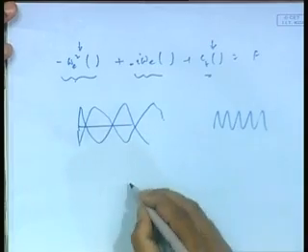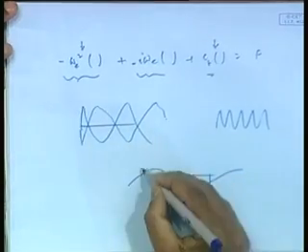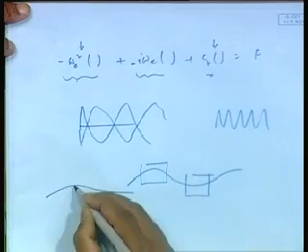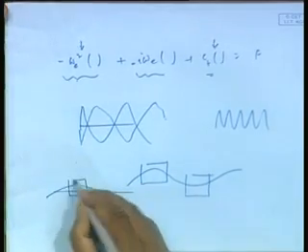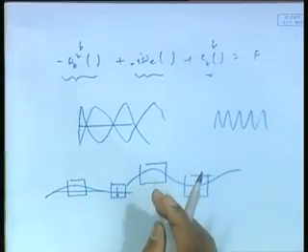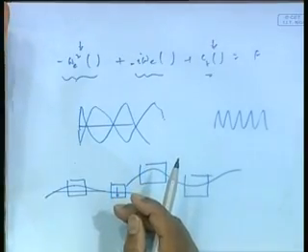This is very important. In the first case my boat was riding the wave, but now at the higher end my boat is out of phase with it. That means, when the wave is rising, the boat is sinking, which is more dangerous. You see, that is what I wanted to tell you from the physical point of view. That means, if I were to draw this here, in this case when the water is rising, my boat is sinking. Here when the water is going down, my boat is rising. So, I end up getting an oscillation relative to the water surface that is much more pronounced, which is of course more important, because just imagine this case, the free surface is rising, the wave is at its crest, but my ship is going down. So there is a chance of water coming on deck, my freeboard is reducing. So, inertia dominated motion typically has a response which is out of phase with the forcing of the wave.